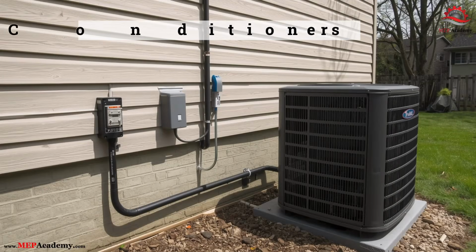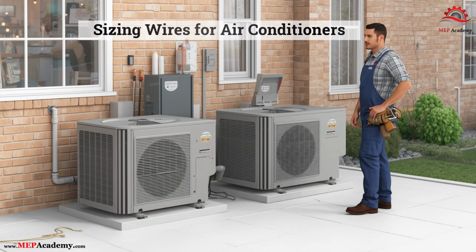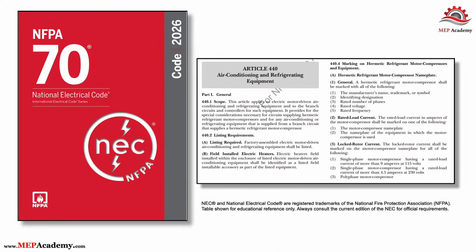In this video, we're going to walk through how to correctly size the electrical conductors for an air conditioner. This applies whether you're replacing an existing unit and want to confirm that the existing wiring is adequate, or you're installing a new air conditioner from scratch. Everything we cover here follows the National Electrical Code, specifically the rules that apply to air conditioning and refrigeration equipment.